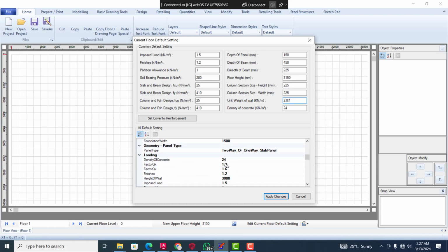Now you can see this is based on British standard. So like what Oga was saying about the Eurocode, the factor of safety for your dead load is not 1.4, and the factor of safety for your live load is not 1.6. Am I right, sir? Yes, for Eurocode, we don't use this. Right? So this is British standard, BS. So you can make reference to this.